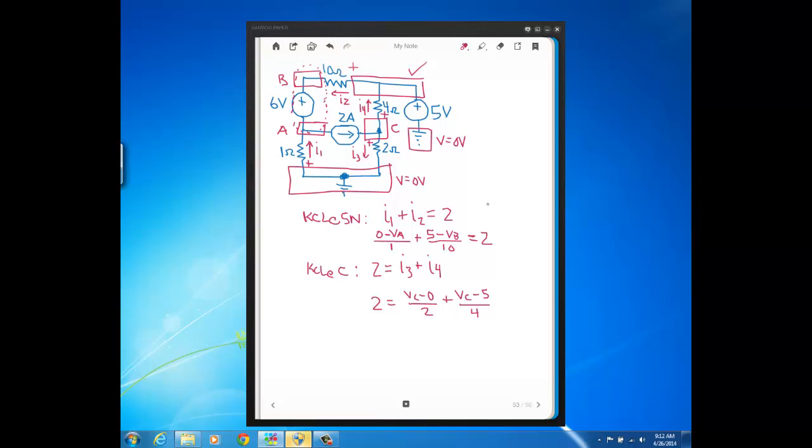So there's 6 volts across nodes A and B, and the higher end side is node B. This tells me that the voltage at node B is 6 volts higher than the voltage at node A. So my third equation is just going to be VB